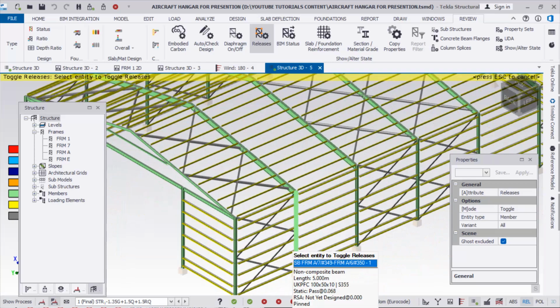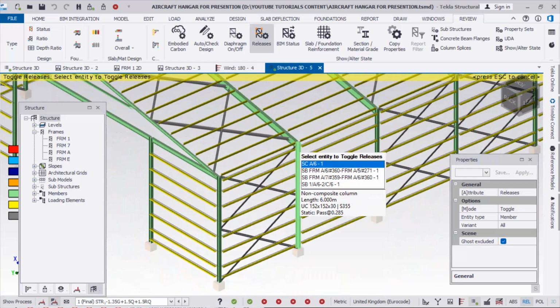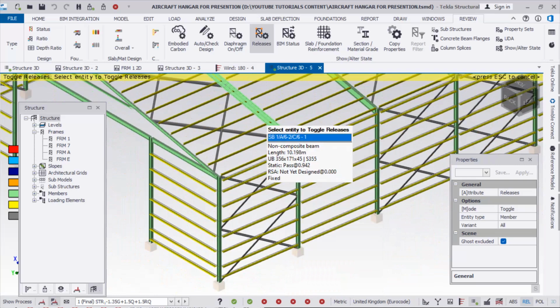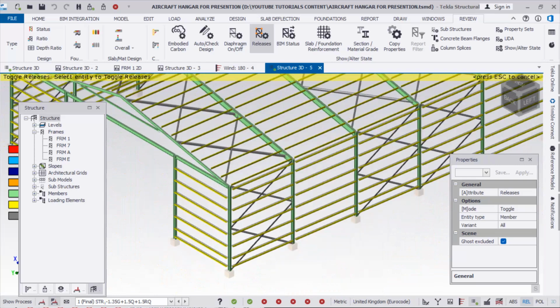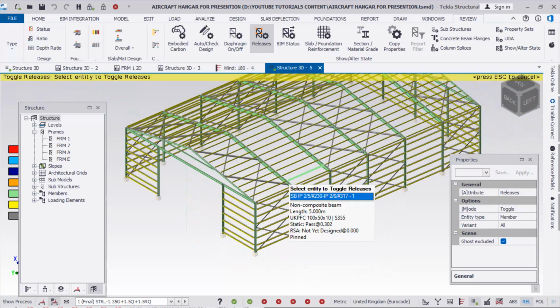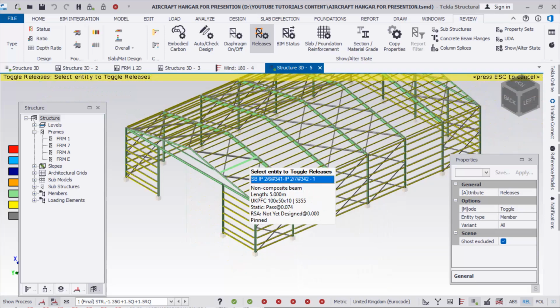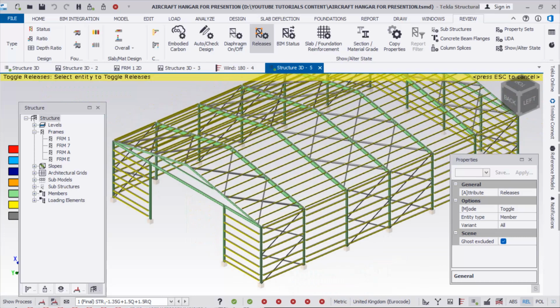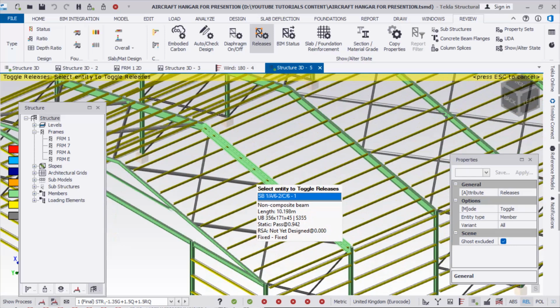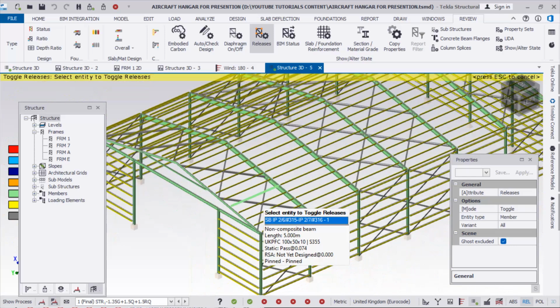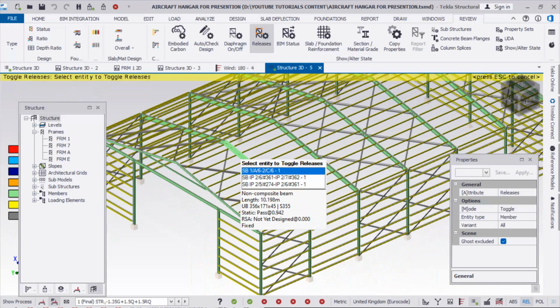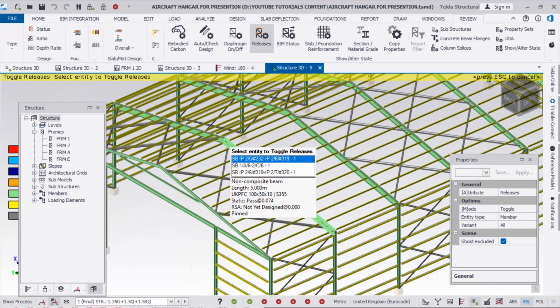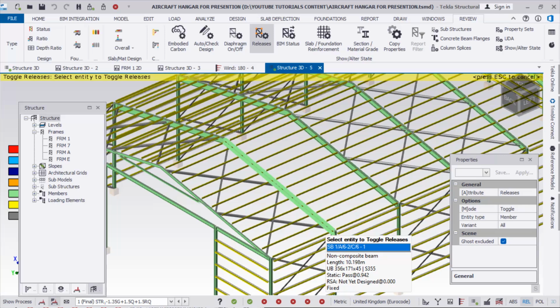But again, if you look at this column here, it is about 6 meters. And you look at this, it's 10.1 meters. And it goes without saying that in this case, for the portal frame structures, it is always important to give priority to the rafters, because when you have your rafters fixed on both ends, what happens is that there is the sharing of moments.